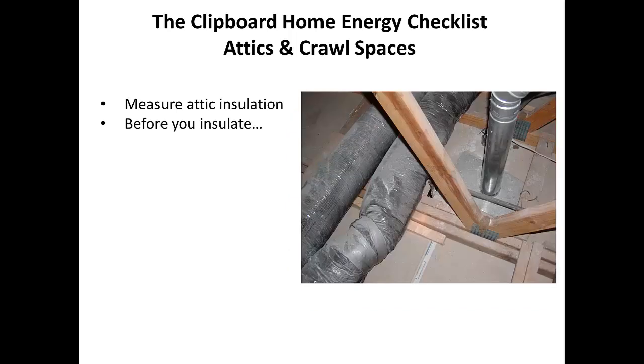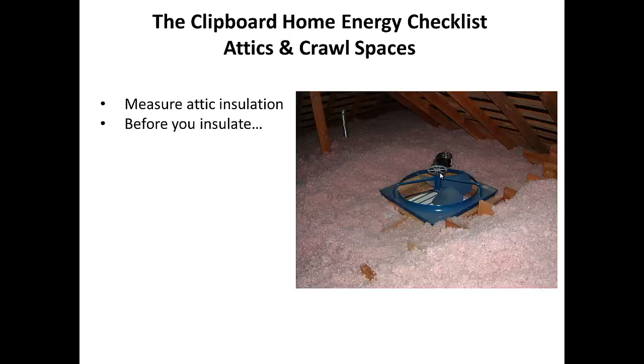Before you insulate, one of the things the professionals sometimes do in older homes is take out all of the insulation. I want you to watch where my mouse is going here. You see this little area here? This is in an attic with no insulation. And see this area right here? That's a hole that goes down into the conditioned area where it's trying to be cooled or heated in the summer and winter time. This is one of those culprits that you want to look for in your attic space.